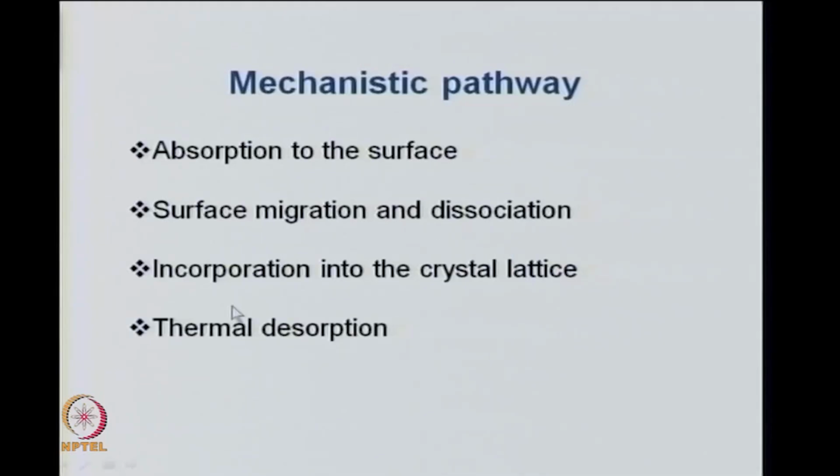Now, the mechanistic pathway during the MBE process is basically adsorption to the surface, then surface migration and dissociation, then incorporation into the crystal lattice and thermal desorption.